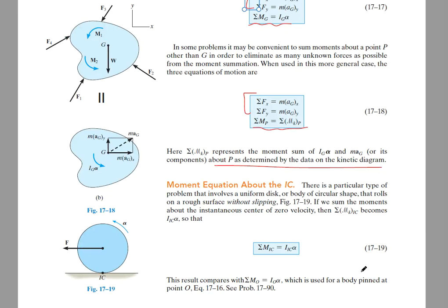Sometimes a convenient point to make use of is the instant center of the moving body, and here you can see that same as in rotational motion, and only momentarily. So same as in rotational motion, you have sum of moments equals angular acceleration times the mass moment of inertia about the instant center. Okay, so a process similar to the one that we've been through when studying rotation about a fixed axis. So similarly, we get an equivalent to the Parallel Axis Theorem, and we can work with this equation, which is simpler in form than this other one here.